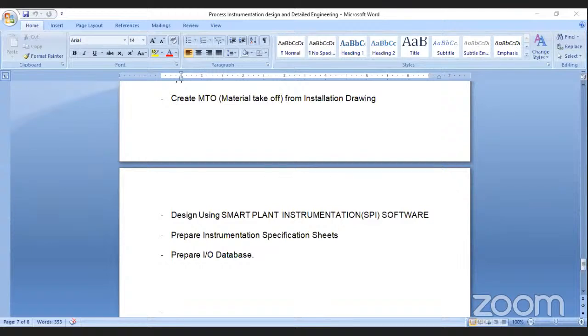In this, the IO list. As a designer, you are in the right position to prepare all the inputs and outputs connected to your automation system. That is the IO list we prepared in the previous course, and we are using it. It has actually become a database. This database is used further in the system engineering for the terminations, the cables and all details, which we enter in this database. Based on the IO list, we'll do the system engineering.